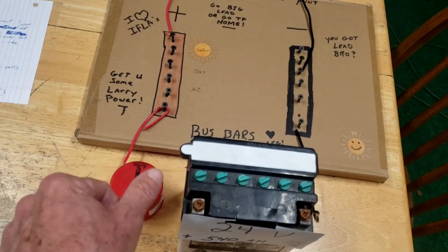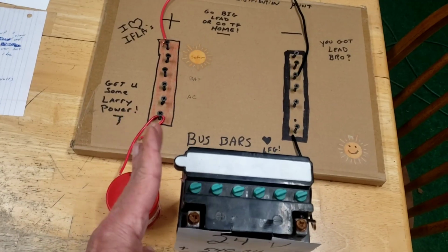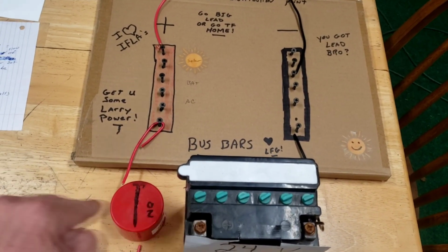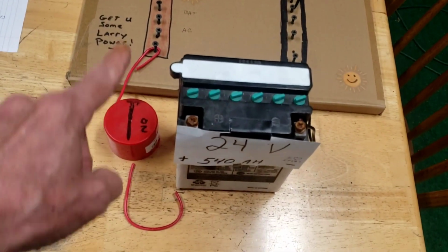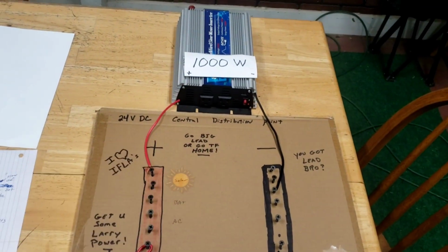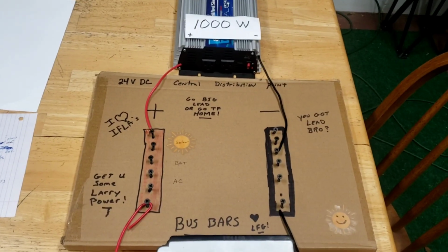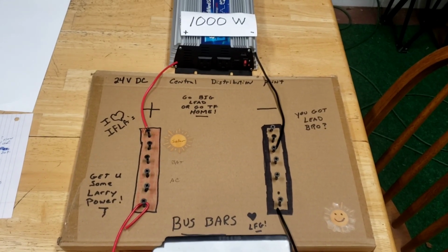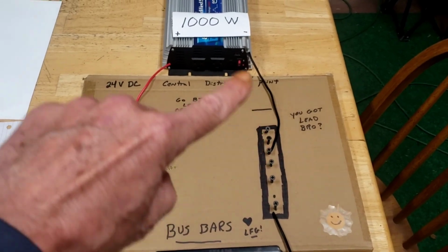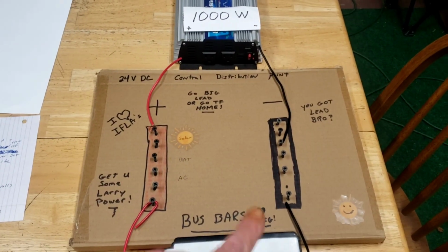And anytime you have one of these disconnect knobs, when the knob is in line with the wire, that means it's on. And when the knob is cut across the wire, that means it's off. So we're on and we're flowing. And like I said, if this runs for 1 hour, this will use 1 kilowatt hour. So understand our flow in our DC circuit.